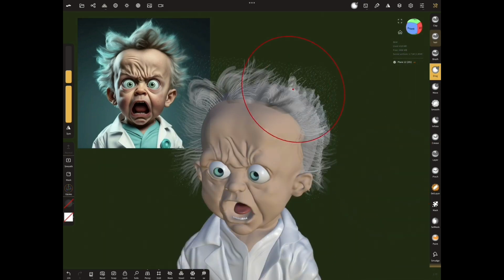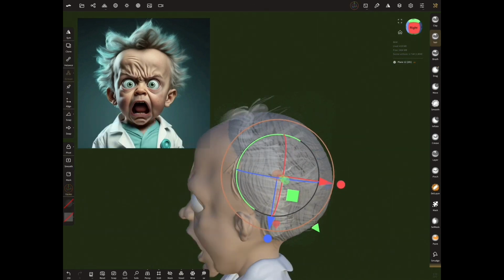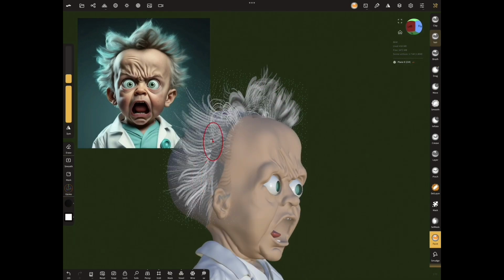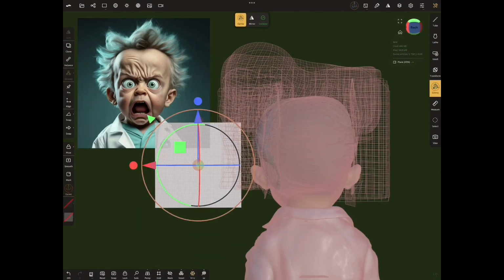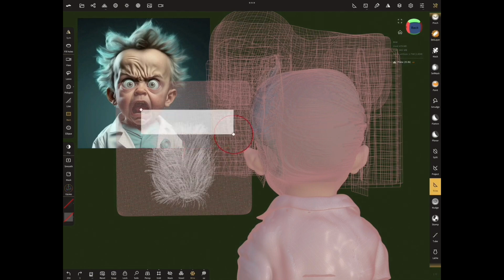This hair texture is only visible from the front. To solve this problem, in the Material menu, you need to set the Two Sides option to the On position. I will make a detailed video about this feature and share it with you. Yes, I have come to the end.